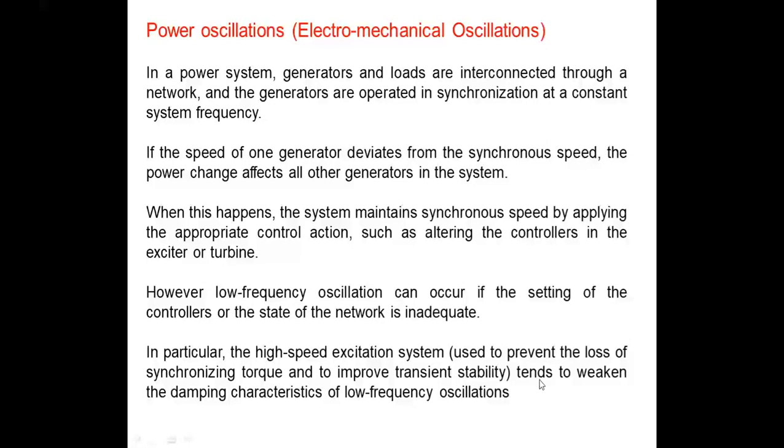But these excitation systems, which are used to improve the transient stability, in another way tend to weaken the damping characteristics of low frequency oscillations. Though they improve the transient stability because they prevent the reduction of the synchronizing torque, we have both the damping torque and the synchronizing torque.